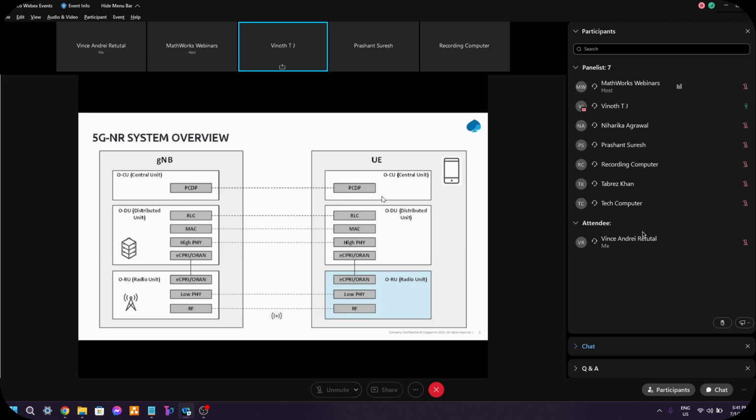Similarly, the L2, L3 processed data will come on the transmit side, meaning the uplink side will get transmitted from here, and it will be passed towards the antenna to this GNB. So this is the major change; people mostly do the GNB based RU design, but in our Capgemini, we have done this on the UE emulator side.